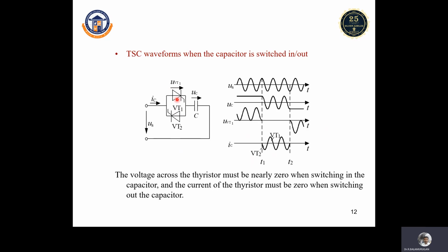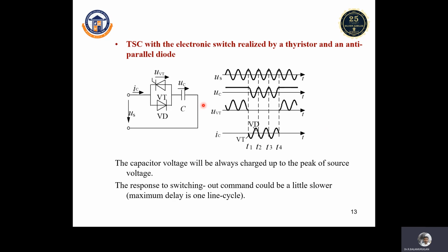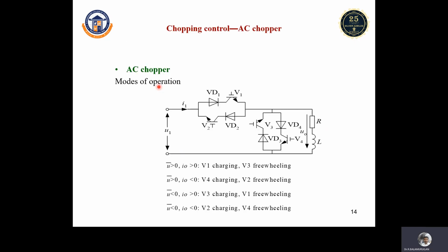Here you can see two switches are thyristors in one case, and in another one switch is a thyristor and one switch is a diode. So here the thyristor controls the output. The diode is an uncontrolled device. So we can call this working operation of the AC to AC voltage controller an AC chopper. This is one of the circuit configurations which shows the output voltage controlled with respect to the applications.